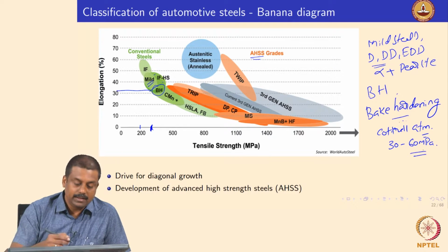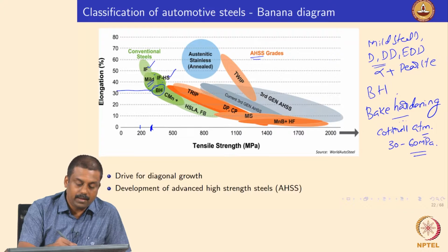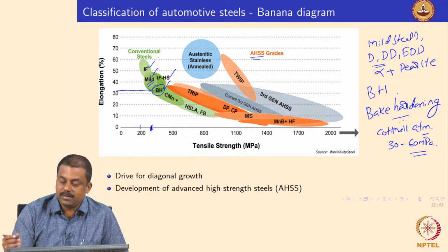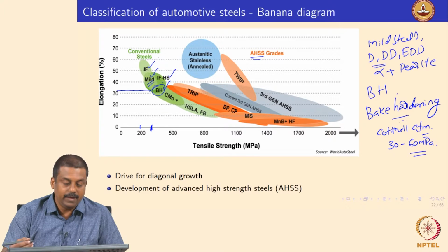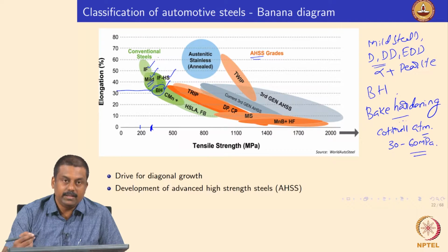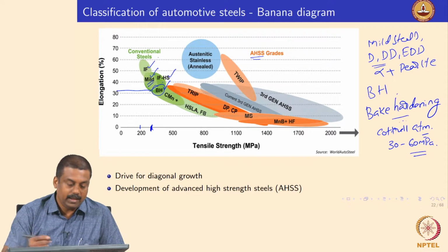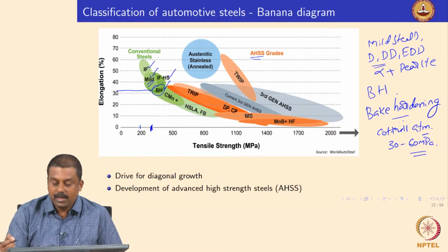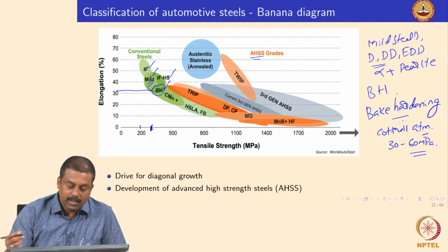So these steels, like IF, HS and bake hardening steels and mild steels, are all now considered conventional steels because they are very simple and they provide very good formability. So the automakers found them very useful because they can form the components with easy mill loads, because of high elongations. These materials can also be made into various components in automotive parts. But as I earlier explained,